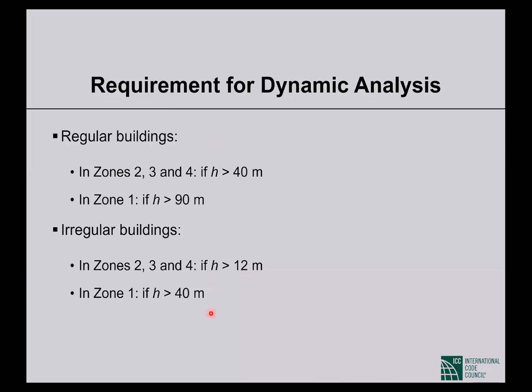I emphasize that the design engineers be prepared, be ready to use dynamic analysis. You may think that it shouldn't be that difficult. The software will take care of that, but that is not the case. You have to understand the dynamics, structural dynamics, if you want to really be efficient in design, if you really understand what's happening.